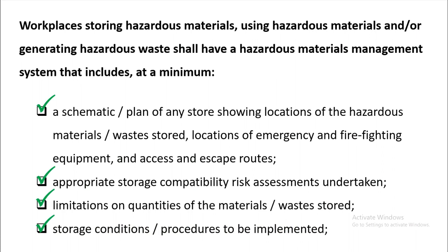Limitation on quantities of materials and waste stored, as I discussed. If you limit the quantity, you are limiting the exposure. So if you don't need a huge quantity of these materials, order only a small amount for your job, and don't bring a large quantity of material to the site that cannot be used in one shift. Okay, because it will expose your buildings and people to the hazardous materials.